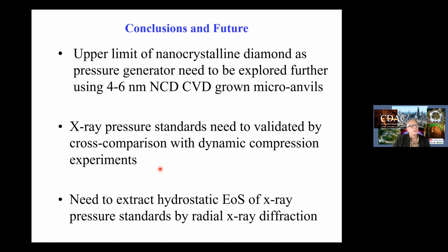Maybe I'll start by saying I was a little surprised at the beginning that you didn't talk about toughness versus strength, because it would seem that your polycrystalline material is actually tough, and you can build in toughness by rapid CVD diamond growth where you want the dislocations present. You want a material that has high strength and high toughness, which has always been a big challenge in material science. And some of these CVD diamonds that we can make by high growth rate methods actually have pretty high strength, but most importantly, high toughness.